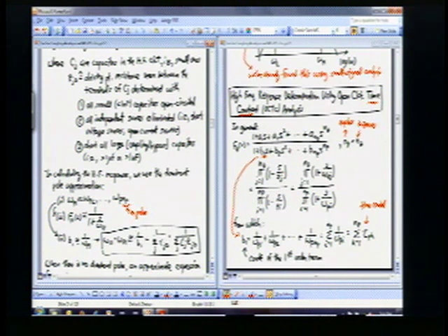Okay, so after I calculate all of these time constants and add them up, I've actually calculated all of this. But I'm going to neglect all of these and say that that's equal to omega P1, and that gives me my omega P1 as long as omega P1 is the dominant pole. If it's not the dominant pole, this doesn't really work. But I will tell you that even if it's not the dominant pole, we still do this, even though it's not supposed to work, because, again, we don't care.